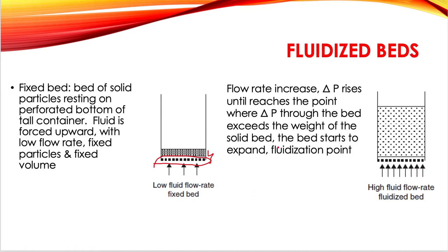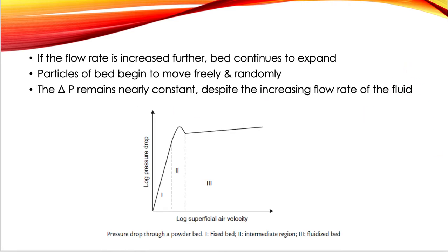As the flow rate increases, the pressure drop rises until it reaches the point where the pressure drop through the bed exceeds the weight of the solid bed itself. At this point, the bed starts to expand, and this is what we call the fluidization point. If the flow rate is increased further, the bed continues to expand and the particles begin to move freely and randomly. The pressure drop remains nearly constant despite the increasing flow rate of the fluid.